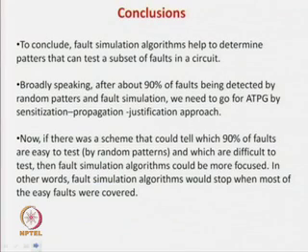We do not carry anything; for a pattern we just find out what are the faults that are detectable in one go. That is why the fault list will have only those elements which are detectable, and then we forget everything, apply a new pattern and do it again.